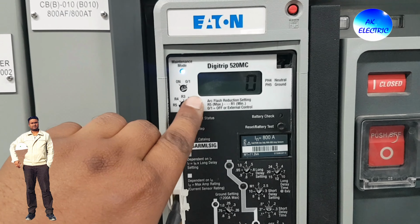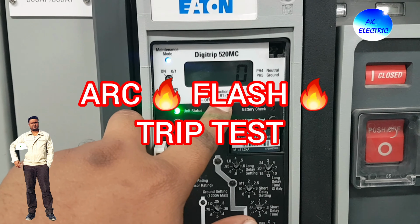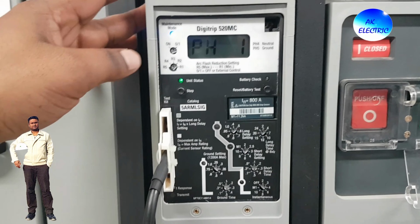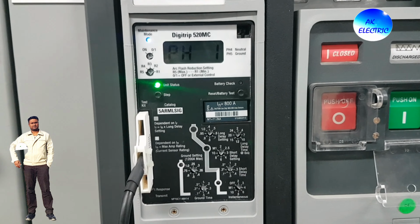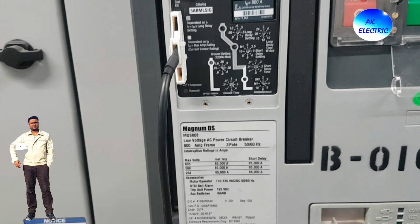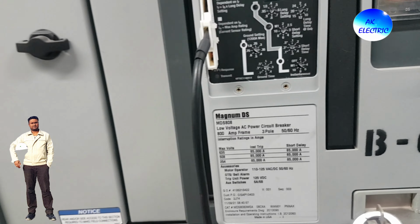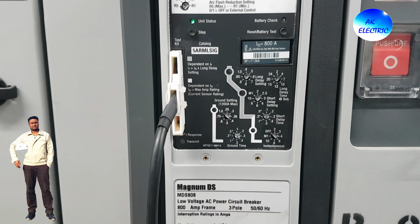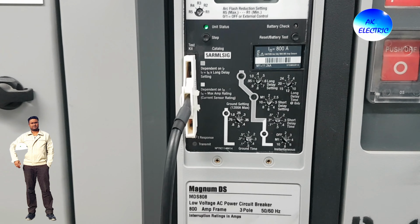So here we have R1, R2, R3, R4, R5. It means arc flash reduction setting. That means if any flashover comes at the breaker backside or busbar, this protection will operate for tripping the breaker. Okay, for this we have to make the settings. All others you can keep in the same position, the long delay, timing, all other settings, no issues. Only you have to make this on condition.